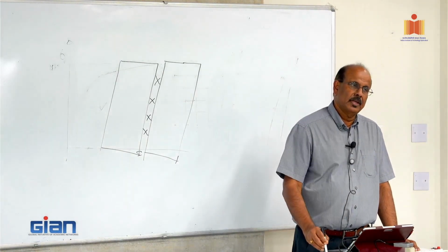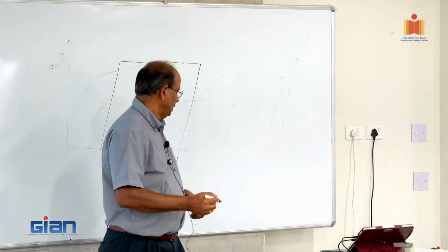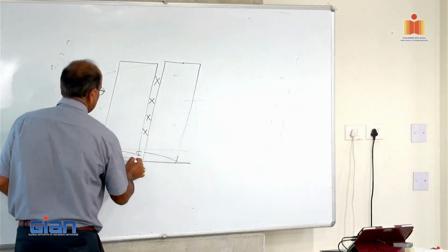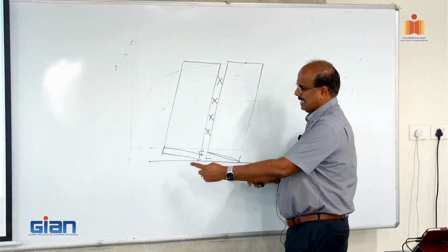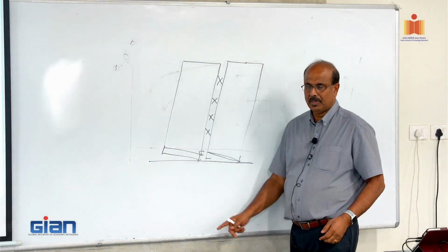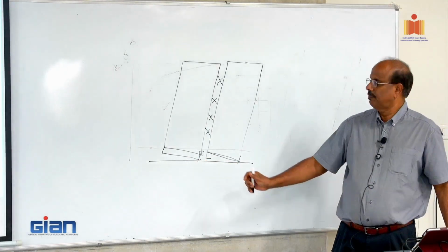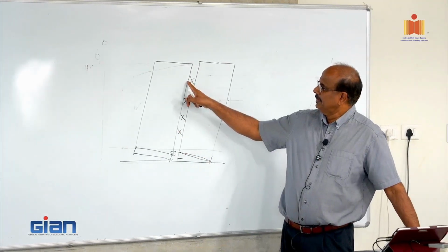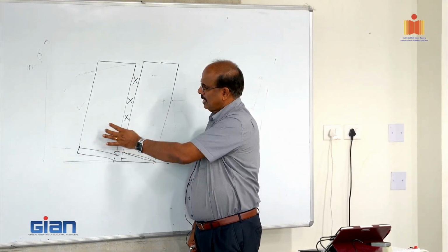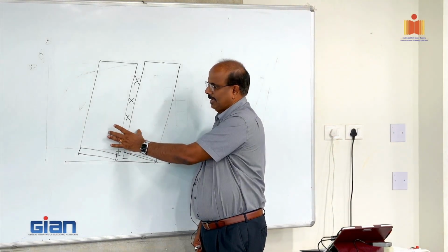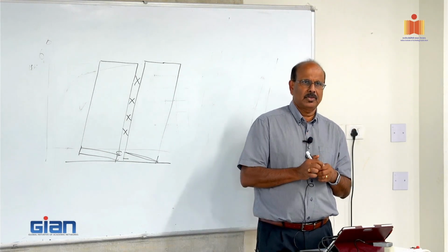One of the challenges, or drawbacks, of the system, which works really well, I'll show you some videos for you to see. One of the drawbacks is that if this is a cast-in-place wall, we would have built it as a single wall, right from here to here. Now you split the wall, it provides some beneficial features, but you cut the system into two different systems. When you do that, moment resisting efficiency actually goes down, right? Because your lever arm gets reduced, right?